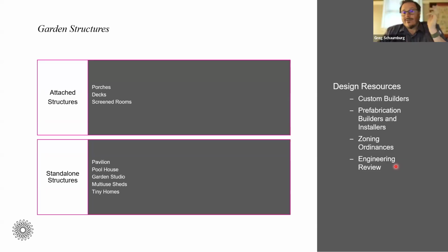And when in doubt, I don't know. I've built a couple things on my own property, and we just had the zoning reviewer come through, and they bumped up our tax bracket because I've improved a few things that were on here, and the reason was structure improvements. When in doubt, look through your zoning ordinance, make sure, because the biggie is zoning is really the stickler, engineering is really the safety check, and those two things work hand in hand.